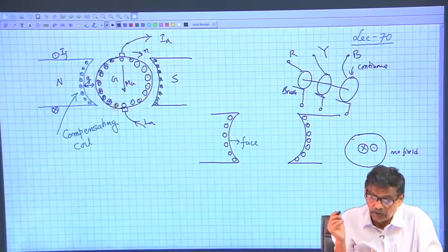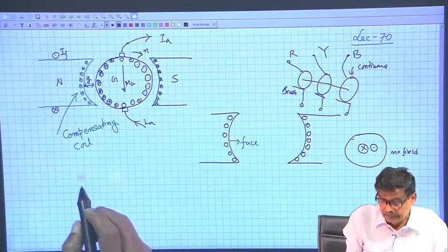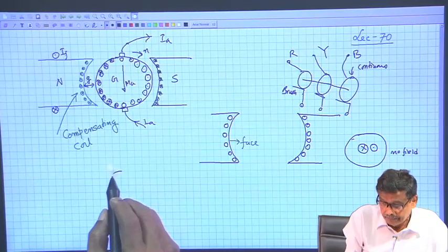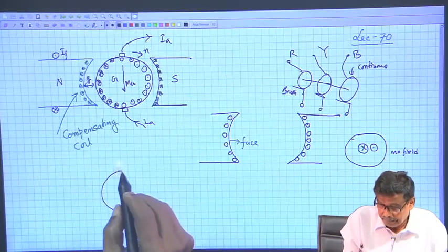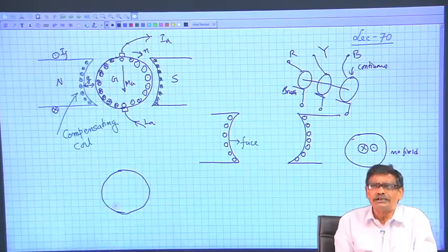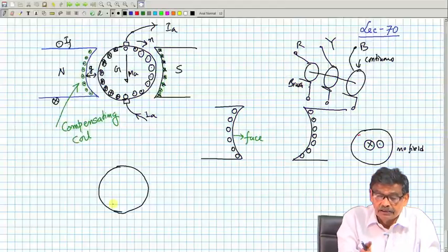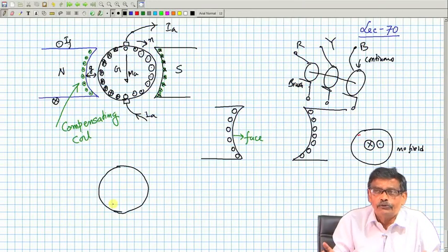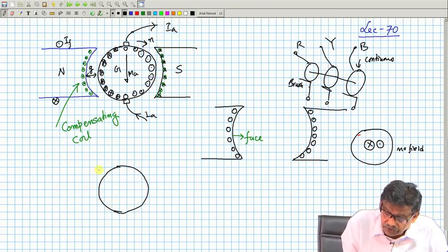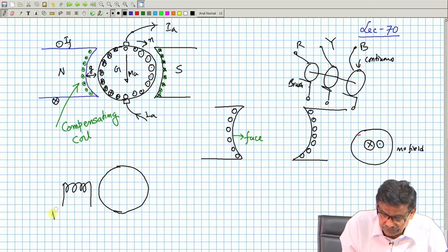Therefore, I should now draw a machine winding, represent a DC machine, large DC machine. For small machines this is not done, because cost will be much more for such machines, additional windings. So what you do, it is shown like this symbolically, field winding, this is F1, F2.